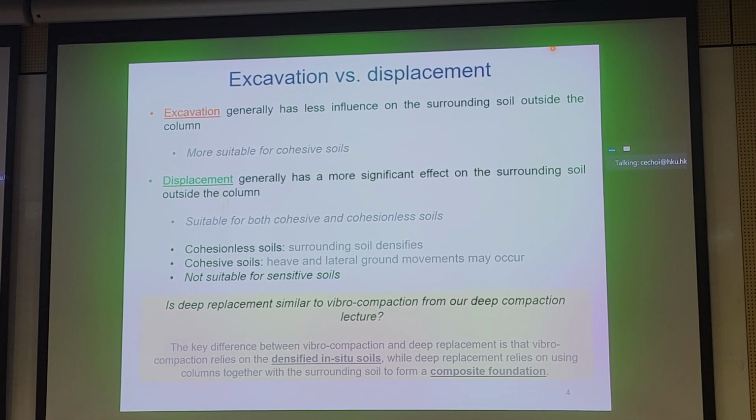When we look at the Penny Bay example later, you'll see that for a particular project for land reclamation in Hong Kong, we very seldom use just one approach. You'll see PVD drains, you'll see surcharge preloading, you'll see dynamic compaction, and these different techniques are used at different locations around the site.